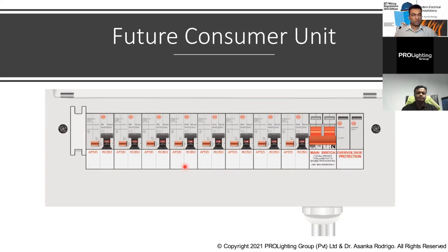Similarly, for overvoltage protection, earlier, since surge overvoltage protection equipment is expensive, people were very reluctant to put it in. But now, as per the standard, you can deviate only if you do a risk assessment and show that there is no transient overvoltage risk. Otherwise, it's mandatory to put in the surge protector. Coordinated surge overvoltage protection is mandatory, and in certain locations it is mandatory whether or not you do the risk analysis, especially where people are working and accommodated, where there is higher risk or public services.